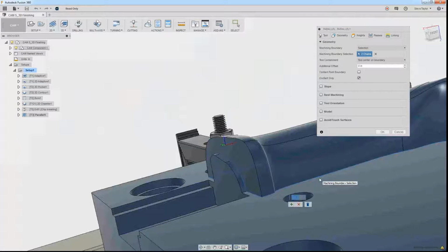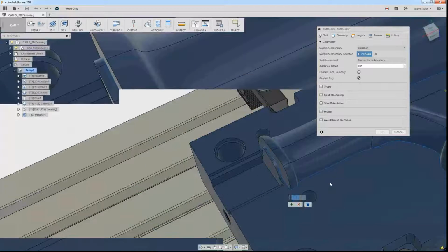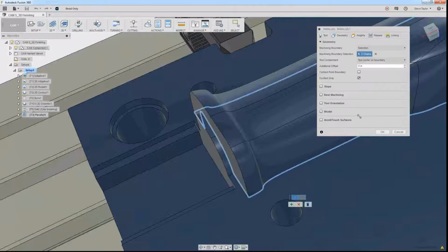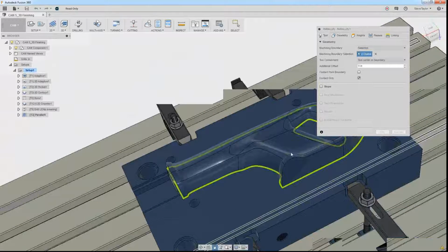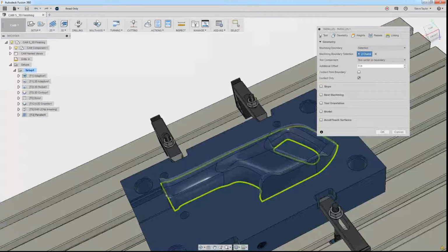So we've actually now got all of the sections around it. There. So if I click plus, that will add now the outer boundary. So we've got the inside of the handle and we've got the outside. We want to make sure, or we've made sure, the contour is closed, but it could be open or closed, but on this one we're going to make sure that it's closed.